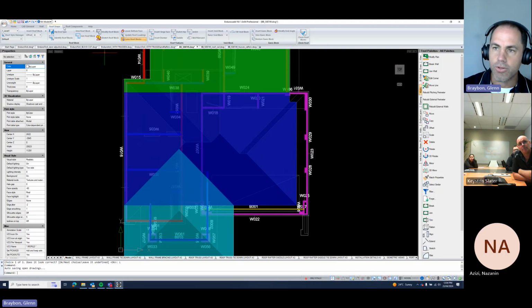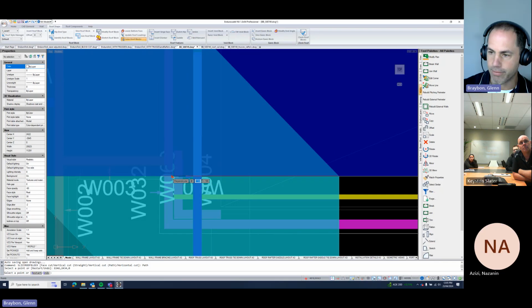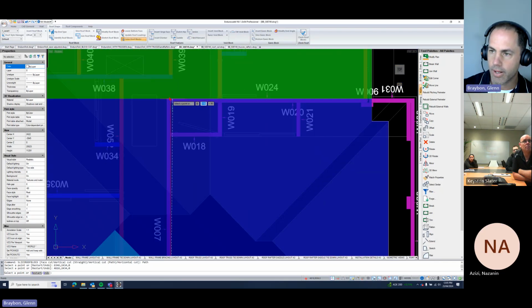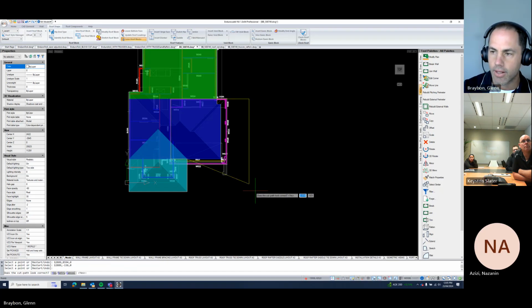Okay, now I'll just do a path cut. I guess technically you could do that as a straight cut, but I'm just going to do a path cut through here. Maybe you might do this path cut before you do the face cut. It's going to run through here. Select a point. So obviously it's good to have orthogonal turned on when you're doing a path cut. We get around and then we can right click to rejoin that path.